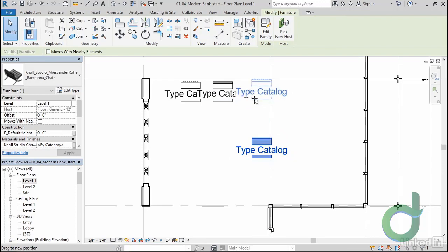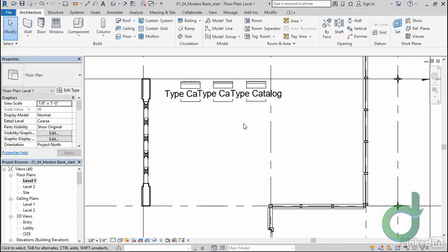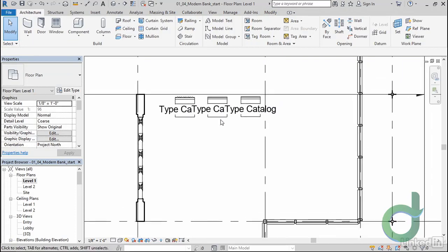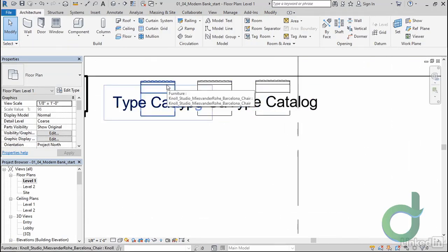Rather than use the Align tool and get them exactly perfect, I want them to be ever so slightly off. They were placed there by people after all. We want them to be pretty close to the edge and just about the same distance apart. This gives us a slightly, perceptibly less perfect feel and makes the rendering feel more natural. If things are exactly, absolutely, perfectly aligned, such as chairs, it can look a little funny. Some things should be perfect, like the column placement. Some things like chairs need to have just the tiniest bit of wiggle.